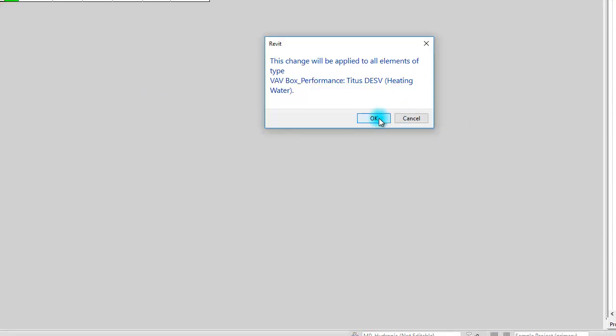You could uncheck this, and now this will turn off clearances on every placed family out there, which is nice because then your tags will attach right to the piece of equipment on the construction documents and you won't have to worry about that.